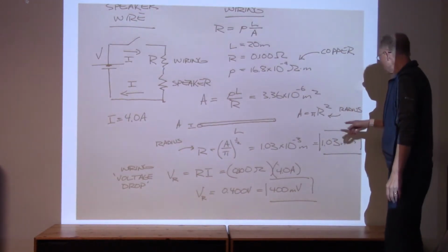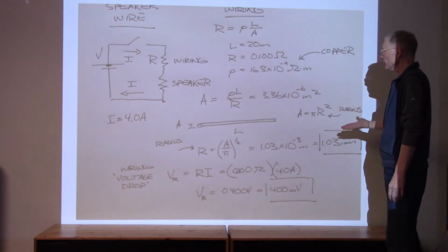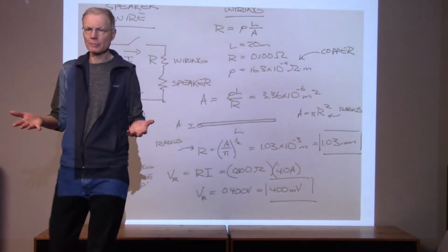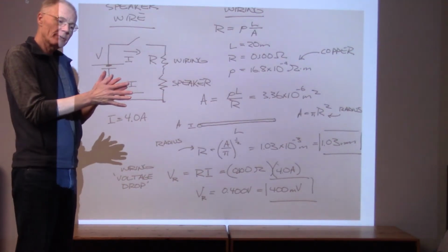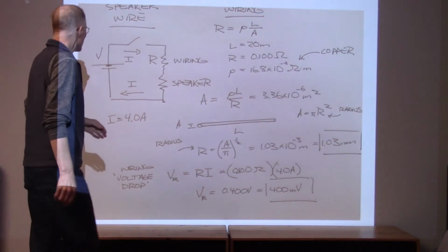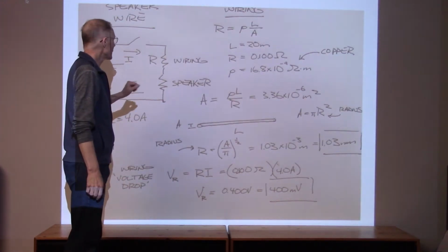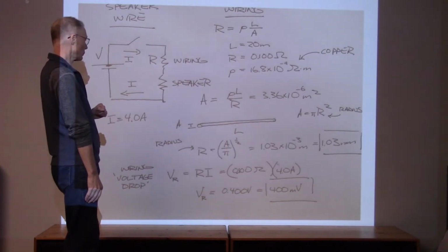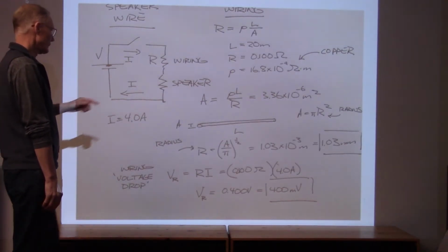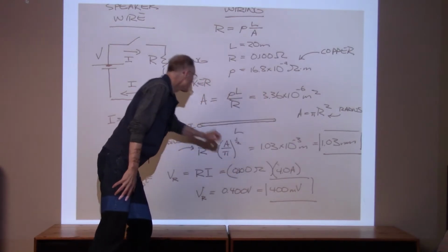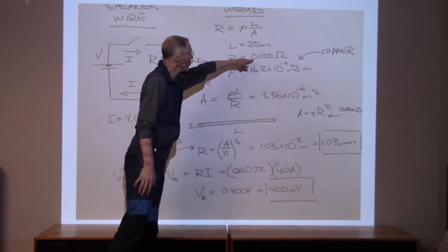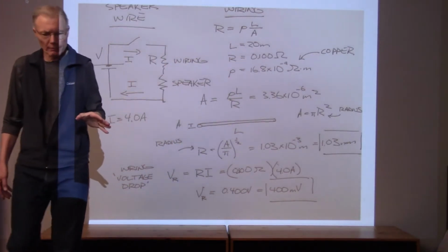So we're finding out how much resistance there would be in a 20-meter length. If we go back and look at that diagram, there are actually 2 wires leading to the speaker. Ooh, I don't know if I did it. The 0.1 ohm is right here. Got it. So the total resistance is 0.1 ohm. That's for a 20-meter length wire.